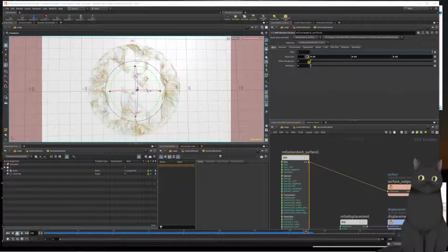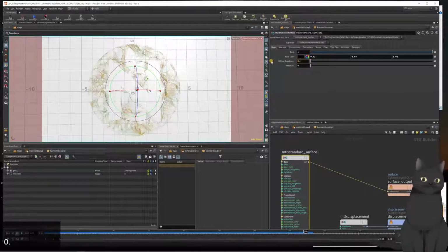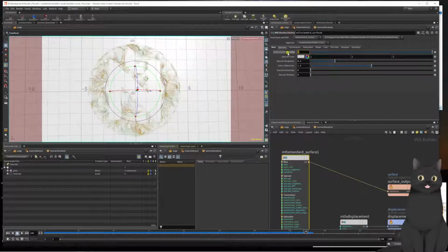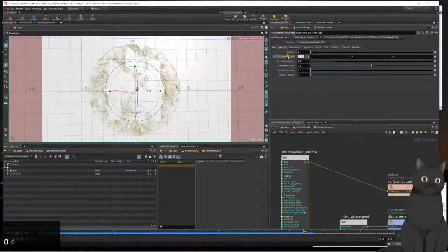A bit to 0.5 maybe, and dial back on the specular to 0, so no reflection. There, and that's it. And to make sure Houdini can properly pattern match the individual materials in here, let's call this one capital BG for back.